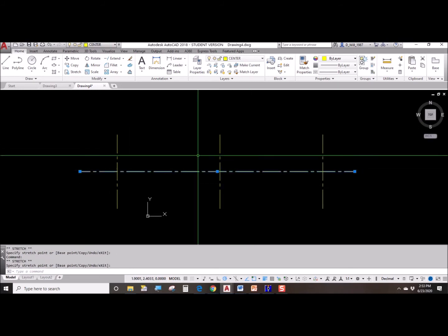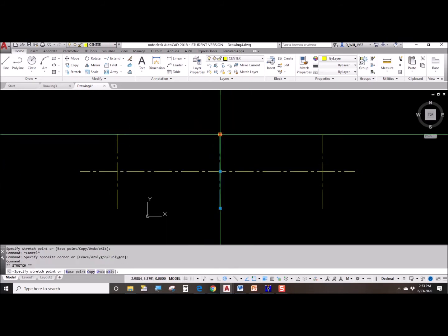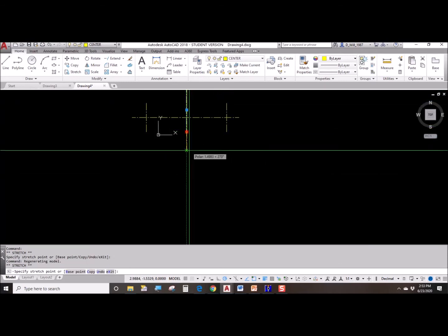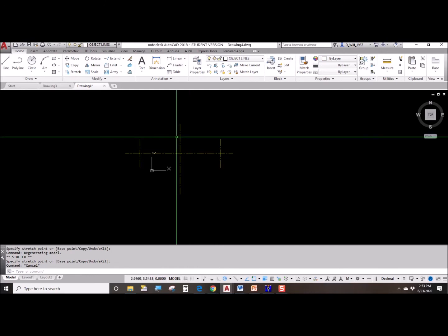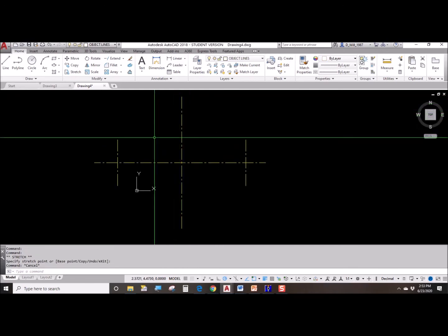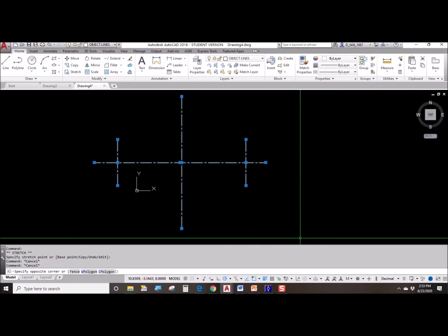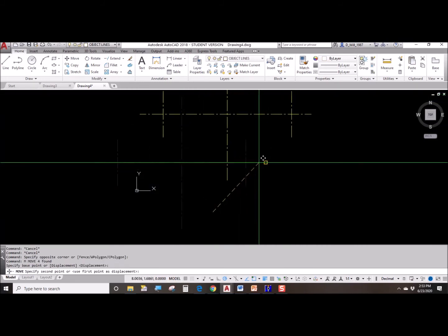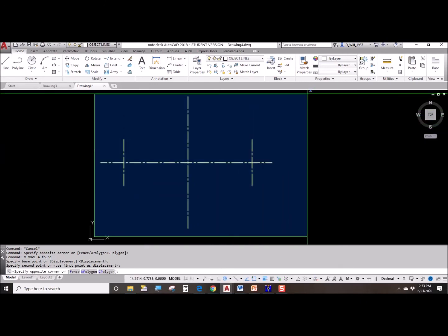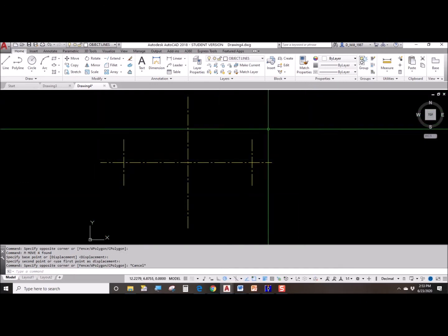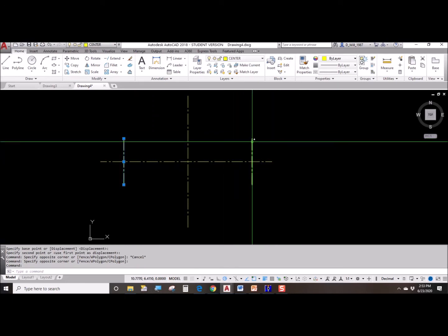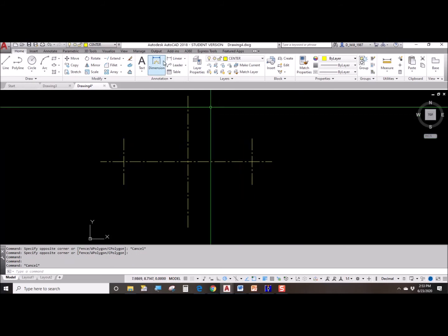And I see that my center lines were a little too short, but you know what? That's fine. You can go in and stretch them when you're done, when you have a better idea of how big the object's going to be. That's what those grips are for. And you can even grab the whole mess and move it up into quadrant 1, which is the positive area out here, positive X and positive Y, to the top and right of the origin. All right, so from the left to the right, it should now be 8.5.